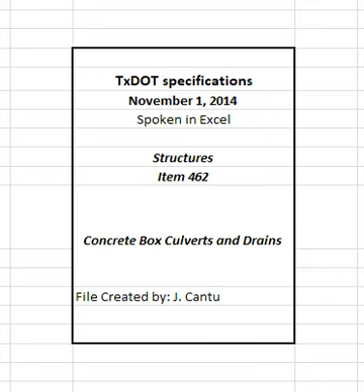Make, cure, and test compressive test specimens in accordance with DMS 7310, reinforced concrete pipe and machine-made precast concrete box culvert fabrication and plant qualification. 2.3.4 Testing equipment. The producer must furnish all equipment required for testing concrete for boxes produced in a precasting plant.